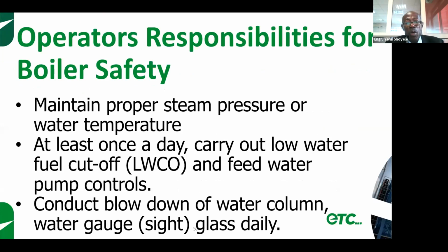This particular one is very key for me. The life of your boiler actually rests on this. If you don't do it, it's a recipe for chaos. Despite all the electrical, electronics, safety devices, this is a true test that when you get into a low water level situation and your boiler feed pump is not delivering, the burner will cut off and the boiler will shut down on alarm.